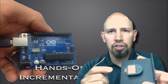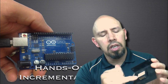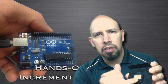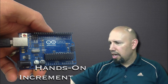In this particular case, you can see that there's a connector that attaches to here, and it tells you exactly what the pins need to be. So this is a very common layout for the pins for encoders. You have a channel B, you have 5 volt. In other words, it requires power, 5 volt, and then there's a ground over here, and then there's channel A, and there may either be something here, it says NC, no connection, or there may be an index attached to that pin. So I discussed what an index was last time, and there was a little video that showed how that worked. So this is an example of an encoder.